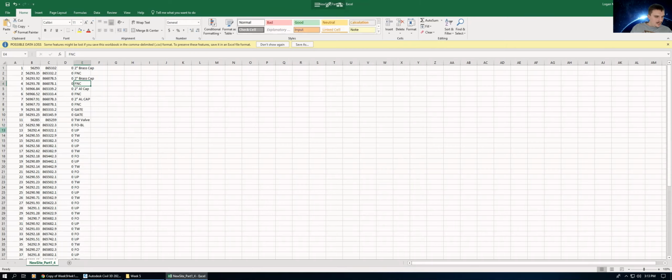So right here on row number 4 on this fence, we should add a dash EL because the fence begins here or begins somewhere and then ends here, okay? Another one we're gonna add is on line number 8, dash EL to end the line. And then line number 13 for this underground power, dash EL.